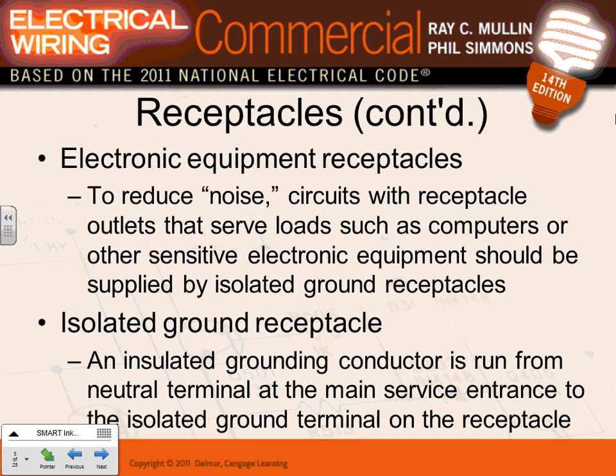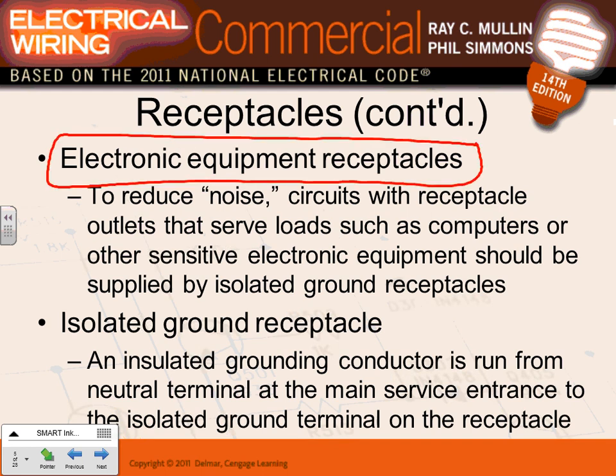There's also electronic equipment receptacles, and we'll talk about those. Receptacles for cashiers: when you go to Home Depot and they slide your credit card and get the money out of it, banks and all this stuff. Long story short, they need a clean ground. That's why they call them electronic equipment receptacles.